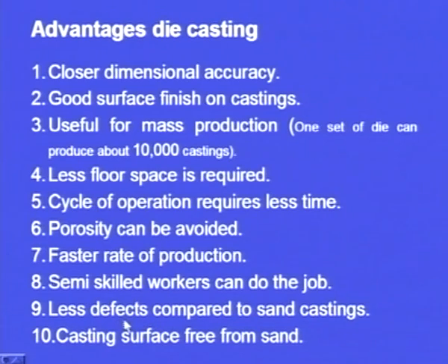The pattern after moulding, it should be withdrawn carefully, otherwise the mould cavity will be damaged. So, at every stage skilled workers are required, but here that much skilled workers are not required to operate this machine. And overall, less defects will be encountered in the die casting compared to conventional sand casting.